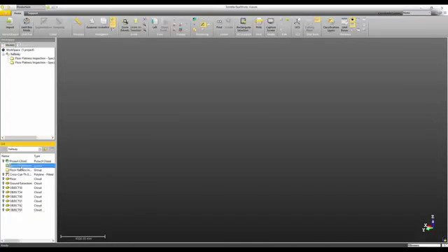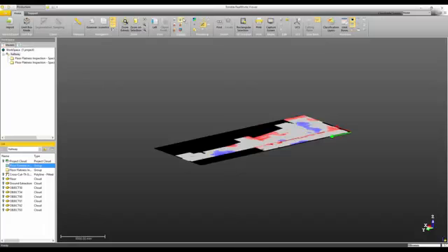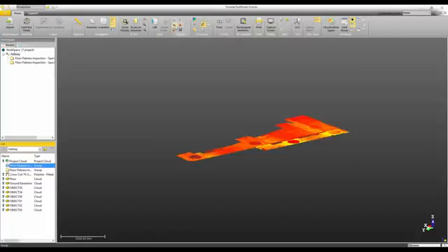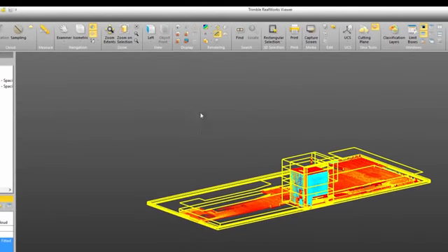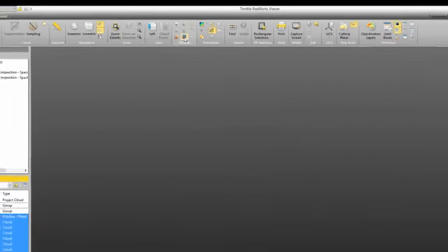But sometimes maybe we have objects in a folder, like here we have 2 objects. If we select that folder, then we can choose to display only the point cloud objects or also display the geometry objects. It also makes it easy to hide objects inside a folder. Simply select the folder and click on Hide Geometry or Hide Cloud. It's also very easy to quickly hide all objects on the screen. Simply click on the blue icon that's labeled Hide All.